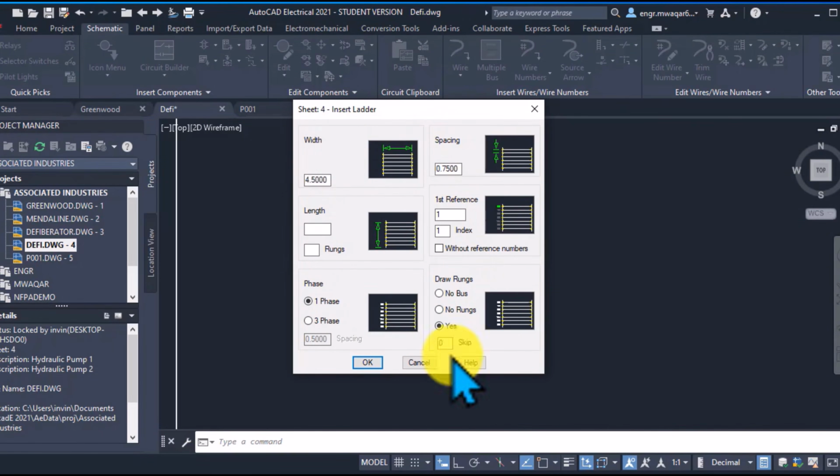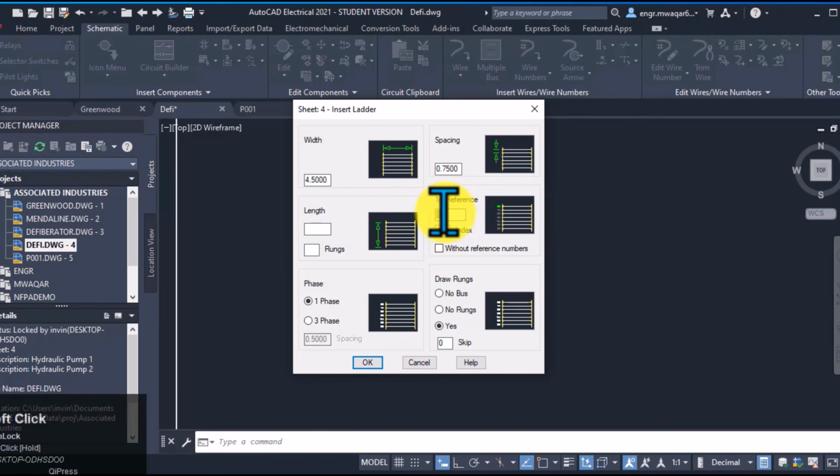And there's also the start index setting. That lets you customize where those numbers begin, right? The software obviously defaults to starting at the number 1, but you can override that. You can, and you often absolutely should. Why? Well, think about a massive project. Say you have 50 pages of schematics for a huge assembly line. You can't have line 1 on every single page. Oh, I see. You'd have 50 different line 1s. Complete chaos. If a technician says, hey, check the relay on line 1, you wouldn't know which page they were talking about. So standard practice is to tie the line number to the page number.